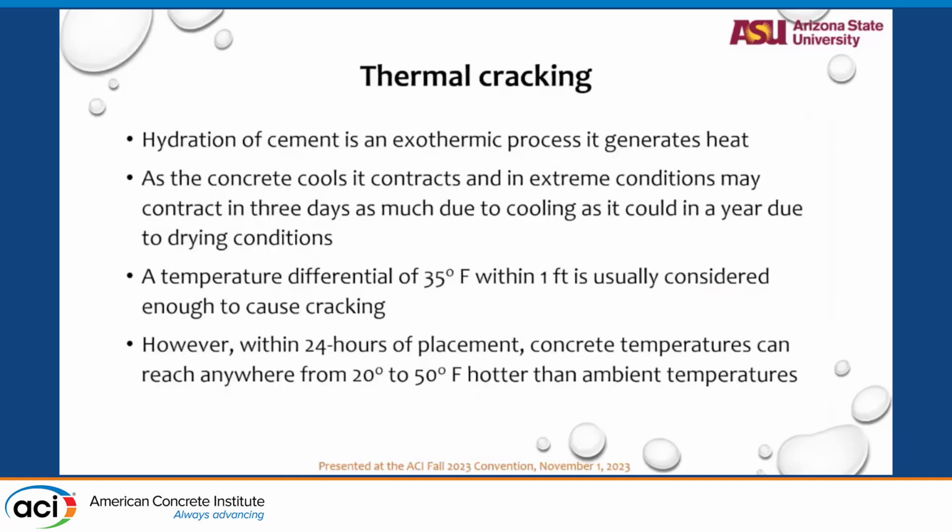So how does thermal cracking happen? Cement, when it hydrates, undergoes an exothermic reaction, so heat is released from the cement. This heat causes the cement to expand, and with the ambient temperature being different, it will contract.